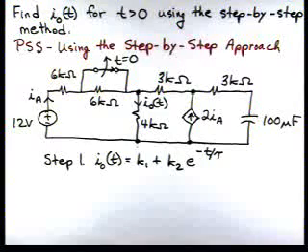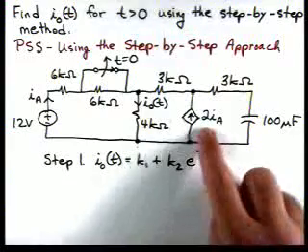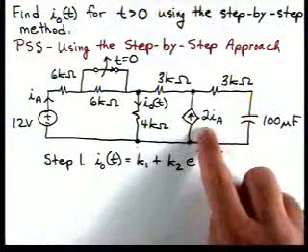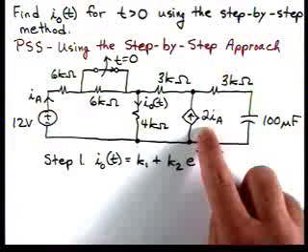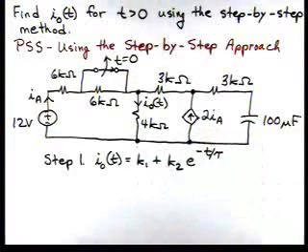We've got a capacitor out on the right hand side. We've got DC sources. Different in this one compared to some of the others is we have a dependent source, so we're going to need to deal with this, and really where it's going to impact us is when we go to calculate the Thevenin resistance seen by the capacitor.